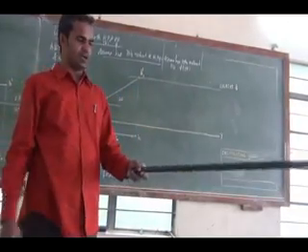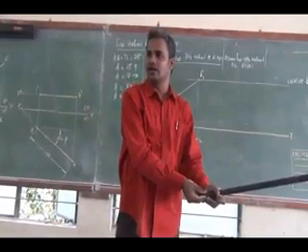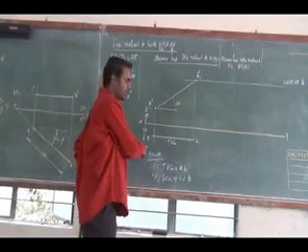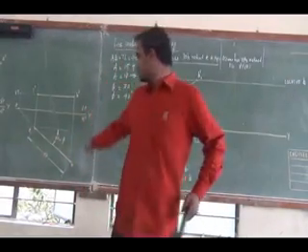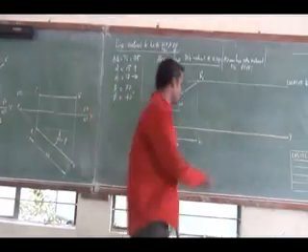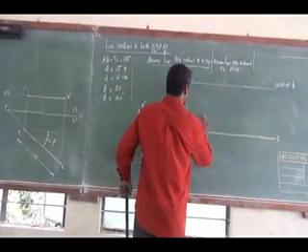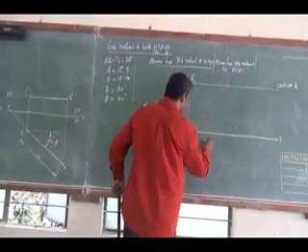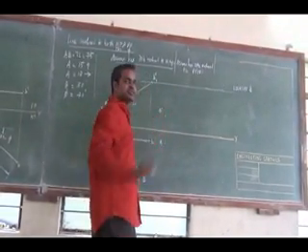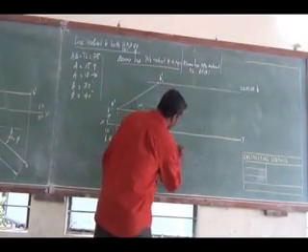You see here, in this one, I will have one end which is fixed. That end location is going to be the same, A dash and A. The other end, as per this, is only inclined to VP. I can draw it like this. The same locus, the end will be here. In three separate steps, I am going to draw it. So this is my end A dash. This is A. It is a fixed line. As per this assumption, the line is 40 degrees inclined.